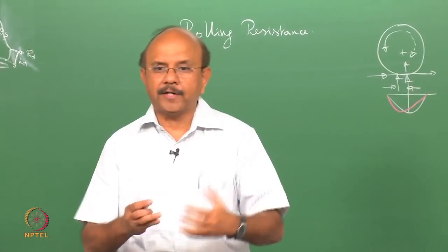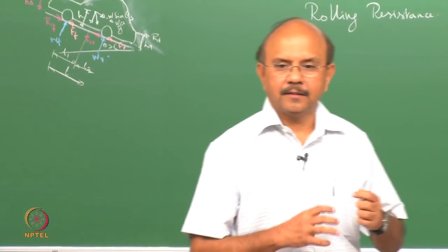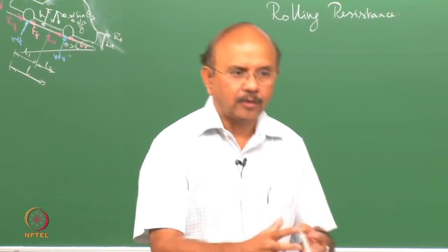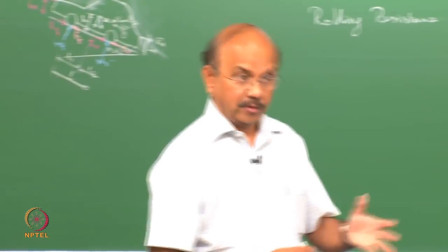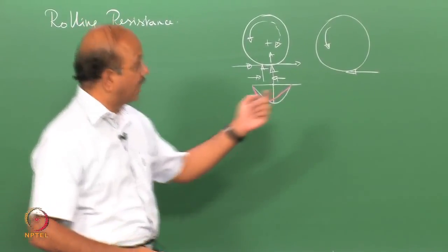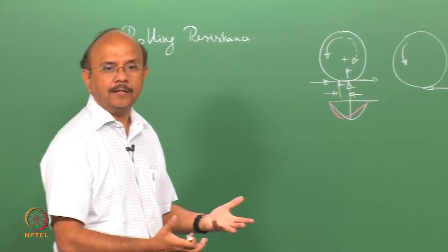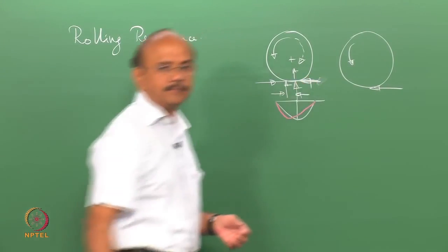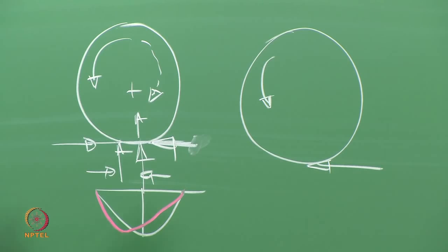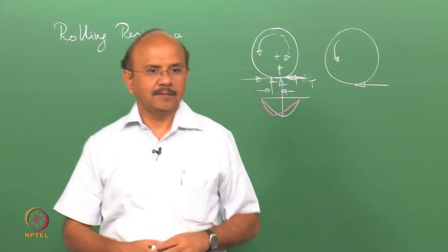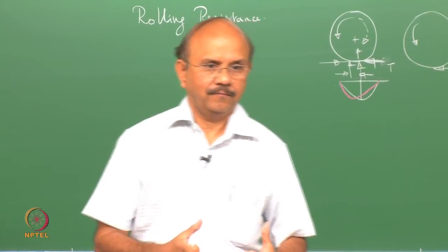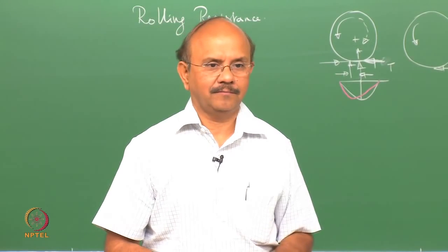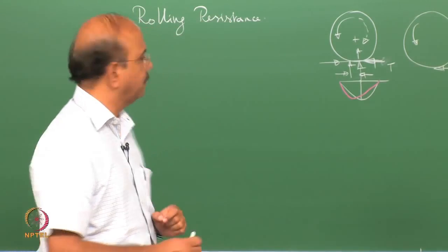So, when I want to put the free body diagram now with the force that has to be acting on the tire, which I want to represent now, in other words the effect of road, like we have effect of trailer and tractor, effect of road onto the vehicle, I have to put a force in the opposite direction. So, hence this force now becomes this. Clear? The force becomes like that. So, this is now the traction force, and that is due to the friction. Okay, we will see how friction holds this. Right, that is the first one.